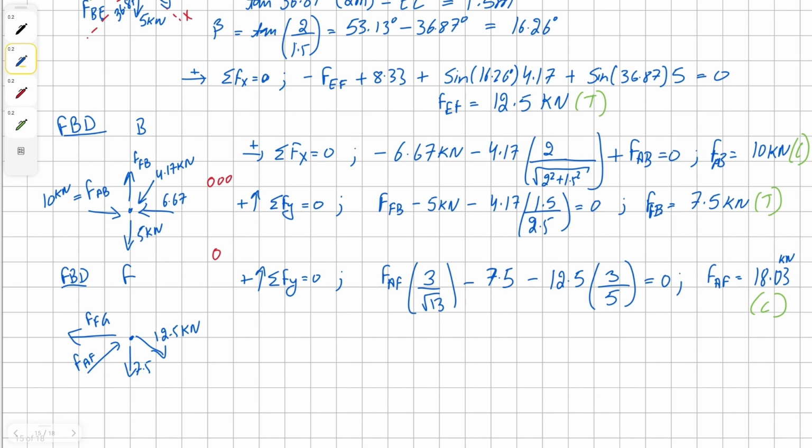Now we can sum the forces in x direction in order to find the value for member FG.